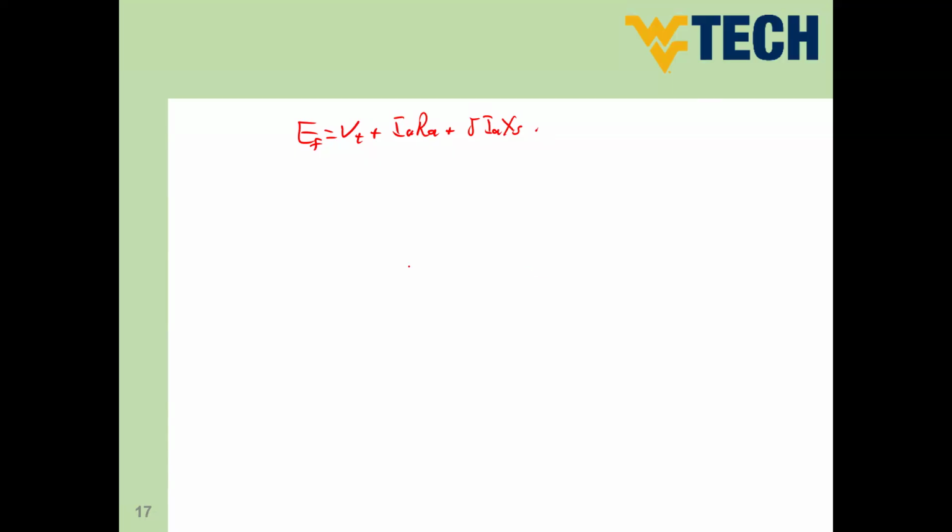First thing is, for any phasor diagram, you have to have a reference. So we are going to assume that V terminal is our reference all of the time. Reference means that V terminal is the absolute value of V terminal, and the angle is going to be 0. So the first step is to draw the V phase.